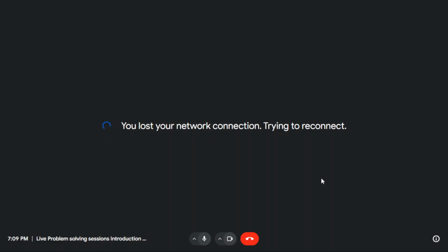Then you can make it with a different material, which you call a heterojunction, primarily used in HBT or heterojunction bipolar transistors, and in low noise amplifiers and those kinds of applications. The second class of junction is the PIN junction, where you sandwich an intrinsic region in between the P and N regions.